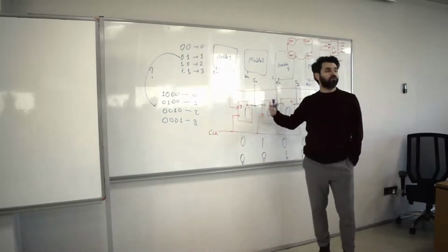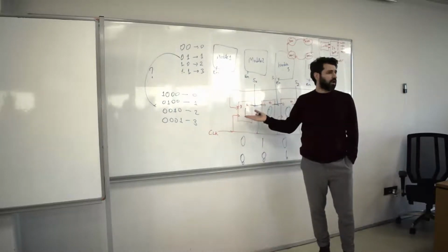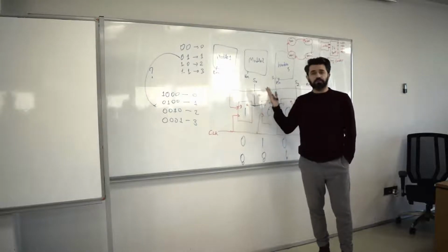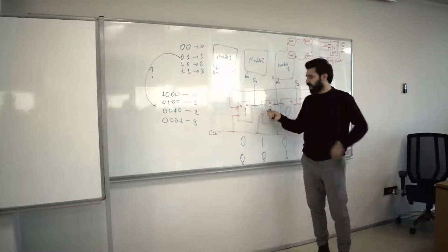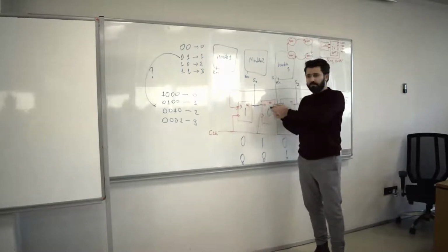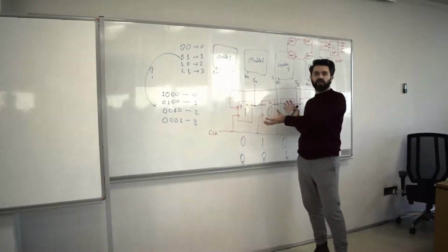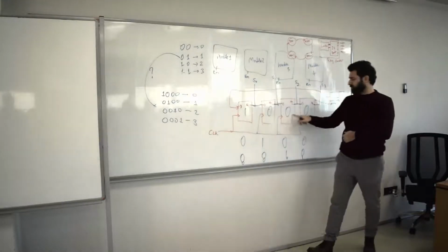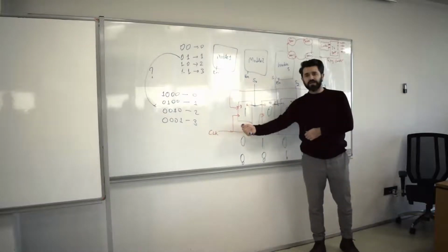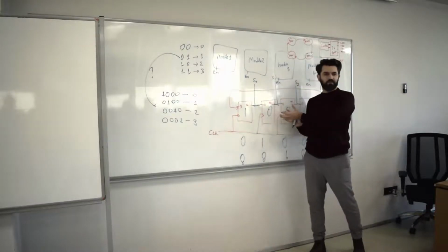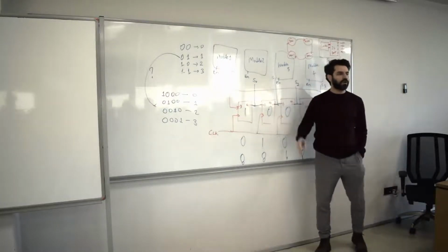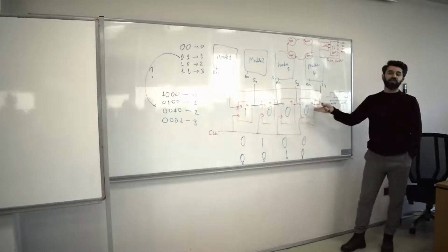Yeah, I assume that I stored that 1 in the beginning of the operation. Yeah, that's a big problem, by the way. I just assumed that I stored 1 by an external mechanism. For example, I connected a multimeter and made sure that this stores 1 before I start its operation. Because if I initialize this circuit with 1, 0, 0, 0, and then start operating it by turning on the clock, then it will not be a problem, because that 1 will circulate anyway and will not change throughout its operation. So therefore, initialization is an issue for this ring counter.